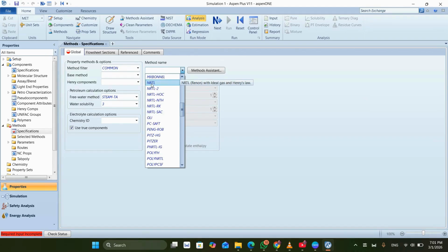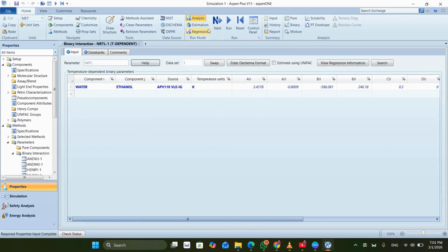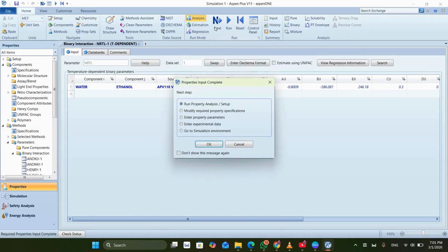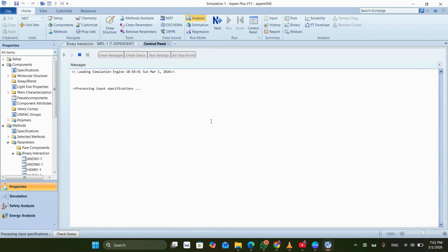Okay, here it is. After that, I have to click next to calculate the stoichiometric coefficients. After that, I have to proceed till everything is successful. So it's running the initial step processes. It will take a bit of time, but it will definitely complete so that we can proceed to building our simulation.